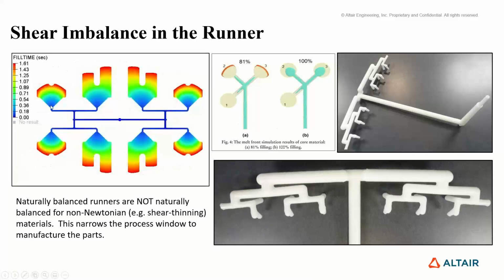So here we can see in simulation, yes, we can capture this in simulation if it's modeled correctly, if you have the correct process parameters, and you've modeled correctly the geometry of the runner system and so on. So if you model it correctly, if you're attentive to the details, you have a pretty decent mesh in order to do that simulation.